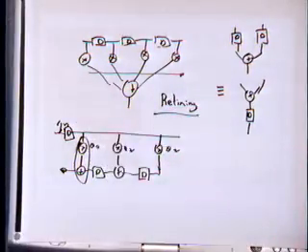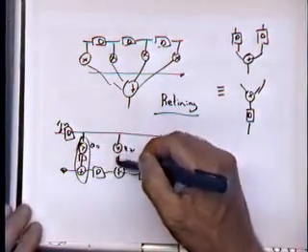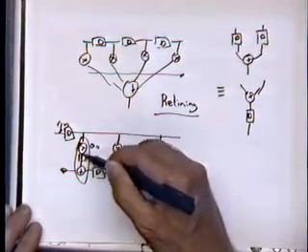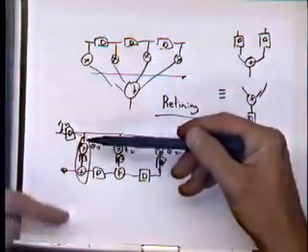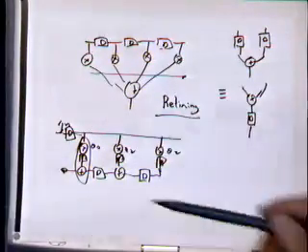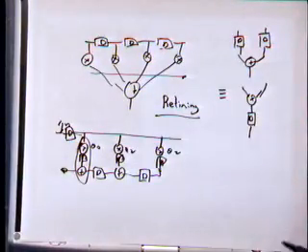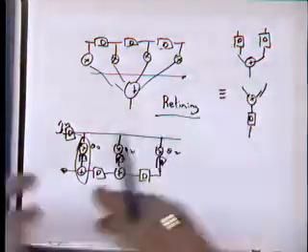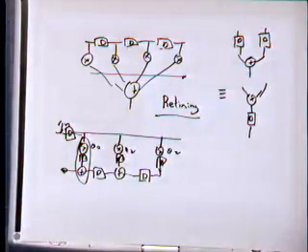Now I can start retiming this delay, and for instance, make it pop up here. So I can actually insert another delay between your multiply and your add, which once again would reduce the critical path. This is called pipelining. You really now start overlaying different computation on top of each other. So it's on the edge. It was not clear in the definition of the project if this was allowed or not. But it was one other way to basically go faster. And you could even go further and put more pipeline there. But at some point in time, the delay of the register becomes the dominant factor, and then you don't gain anything anymore.